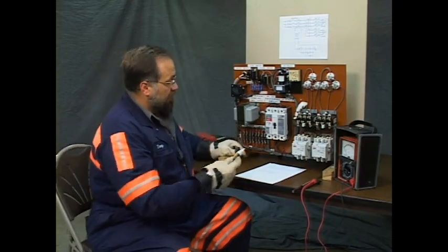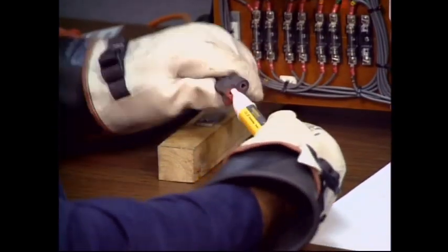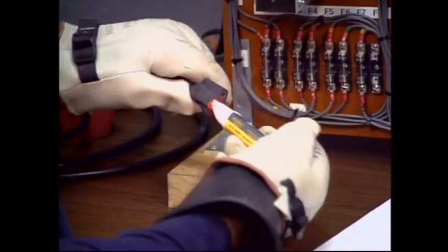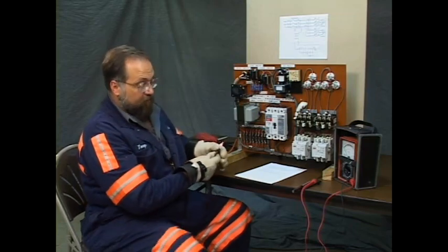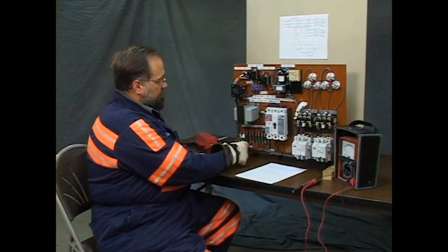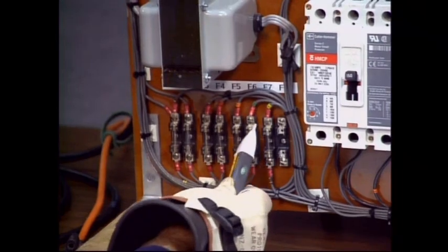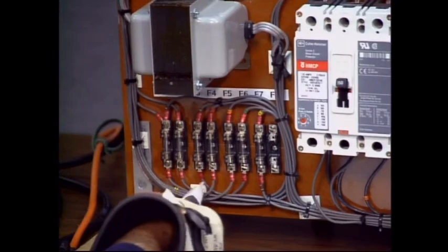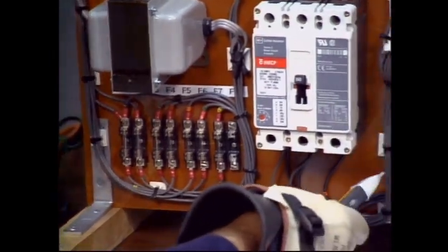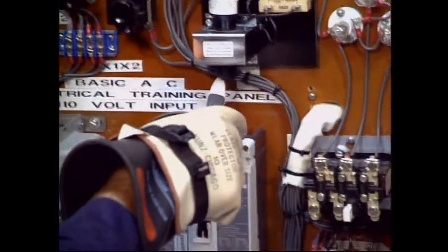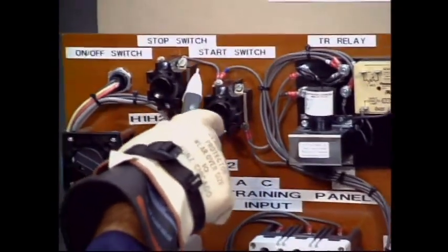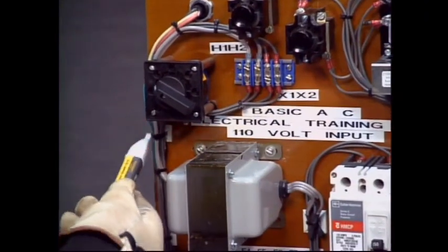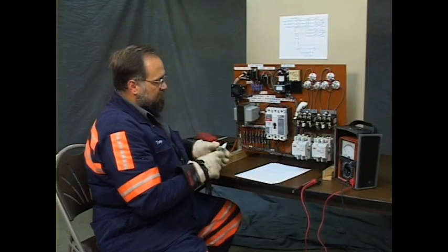To test my voltage detector, I'm going to check it on a known live circuit. It indicates power. We have a constant light as well as a tone. Very annoying tone. Let's try this. Note the intermittent flash, little pulse. That's to give you an indication that the voltage detector is turned on and it's working. It's not detecting voltage. We saw what that was like: a real loud tone and a constant light. Not flashing, but on, period. This doesn't show any power.